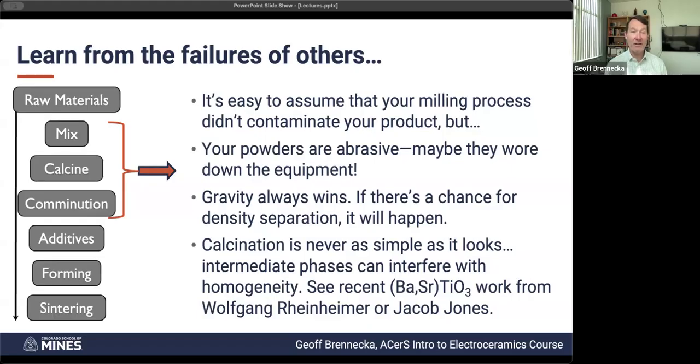You're either using other ceramics as the milling media and as the mills, or you're using polymers that are getting abraded a little bit. Big deal if you get a little bit of your Nalgene bottle mixed in with your powder, it's just going to burn out. But what if you're using steel? You just contaminated your sample with iron and chromium. Keep those in mind along the way.